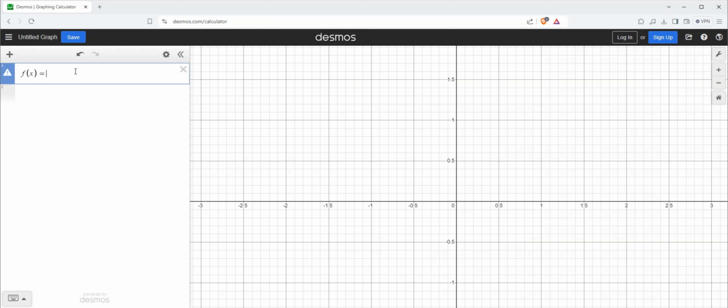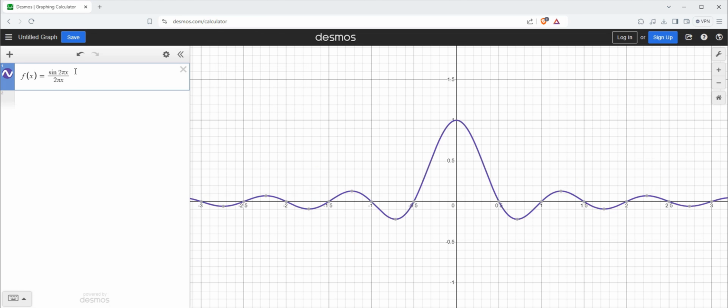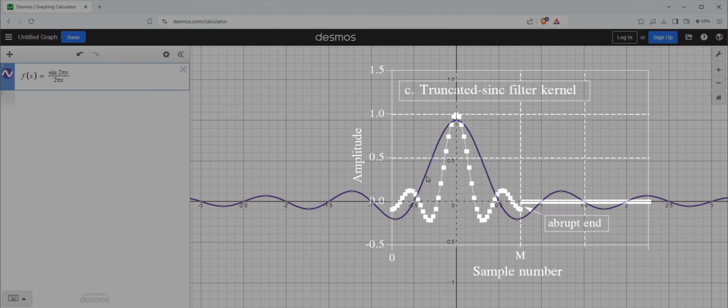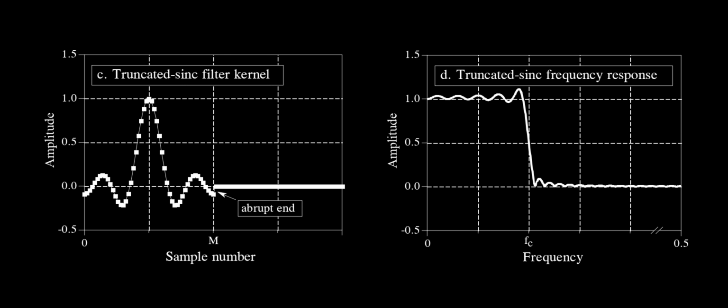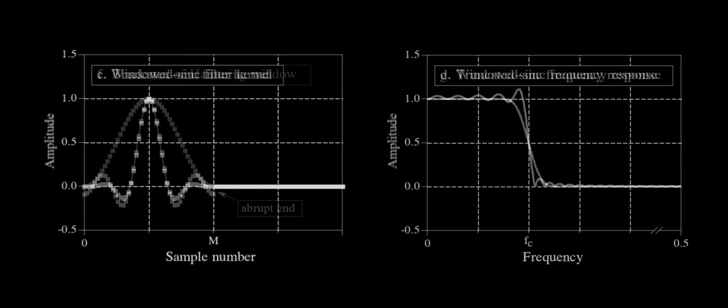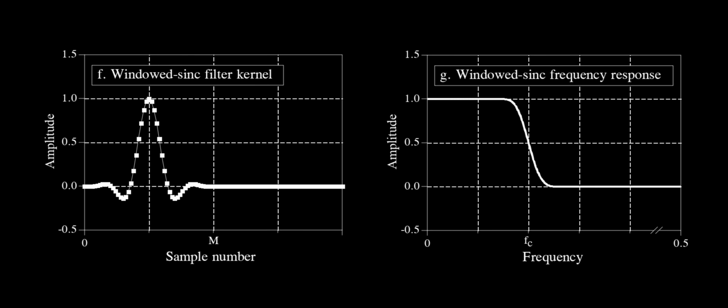Luckily, mathematics has already provided us with the tools necessary to calculate appropriate coefficient values. The sine cardinal, or sinc, is basically sine of x divided by x. The coefficients for an ideal low-pass filter are just the discrete values of the sinc function at certain points. Of course, there is an additional complication. Since we are basically truncating the function at both ends to fit it within a given number of coefficients, a non-ideal response results. For this reason, the entire function is gracefully tapered by a windowing function.